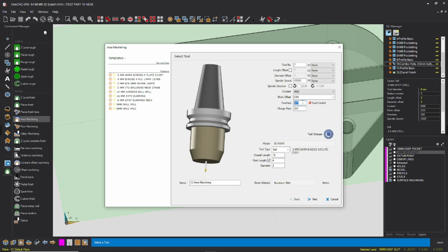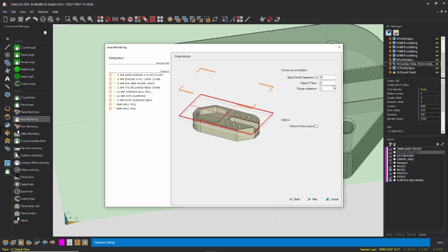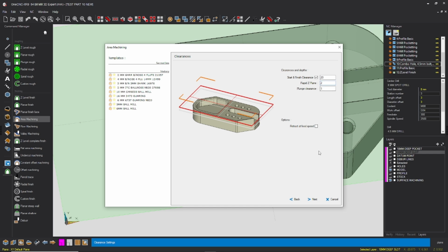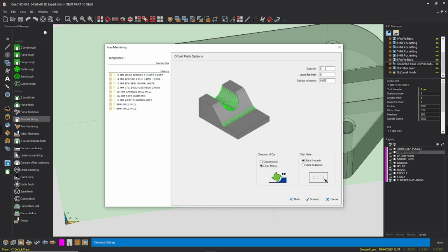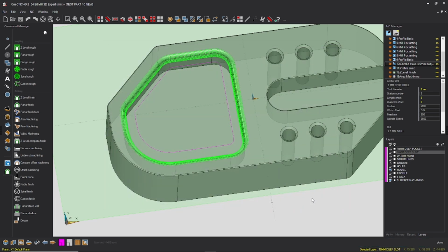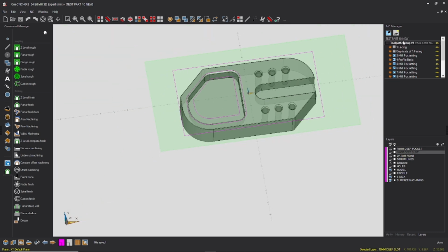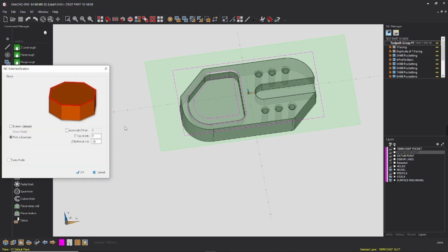So for the feed rate, we're going to go feed rate 600 on there. I'll leave the plunge rate, I'm going to put it 500. I shouldn't do any plunge cutting, but let's go 20. Z2, plunge clearance 1. That's fine. Step over, I'll go 0.2. Leave finishing 0. Yep, click finish. That's simple. Click save. What we'll do is we'll just turn our stock on quickly and we'll simulate our op 10, and then I'll show you how to flip it over and do your op 20.